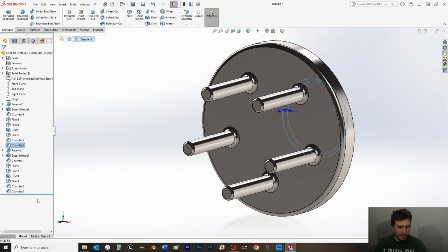So, this is to show you that you technically could make the part twice and then check to see if there were any errors. Like if you wanted to have somebody demonstrate drawing it, and then you just roll back, model it and see if their features match up to this. At this particular juncture, I'm not going to mention why you would want to use this feature, but now you know it exists. I know I've gone over rollback before.